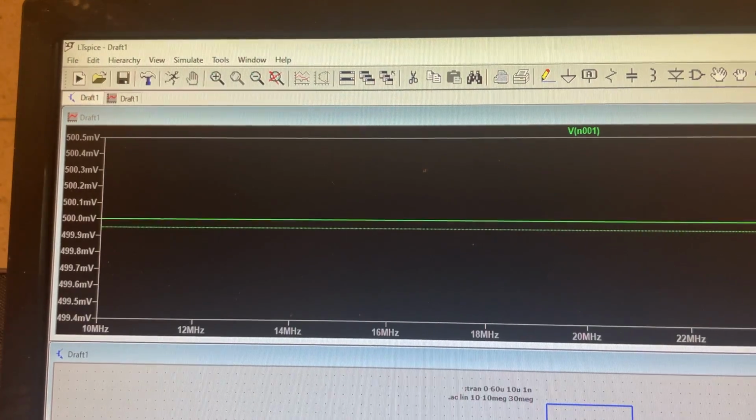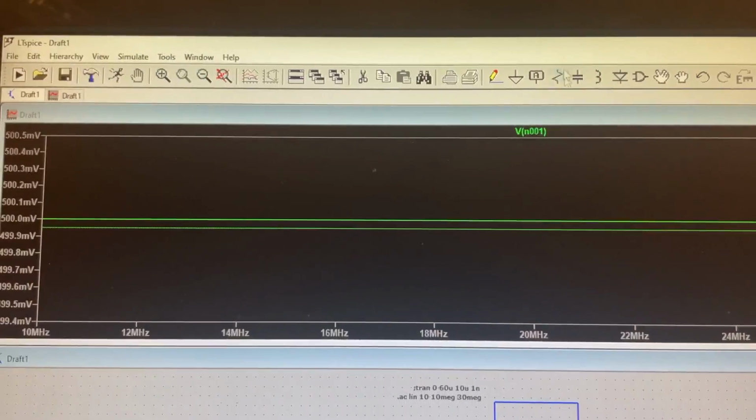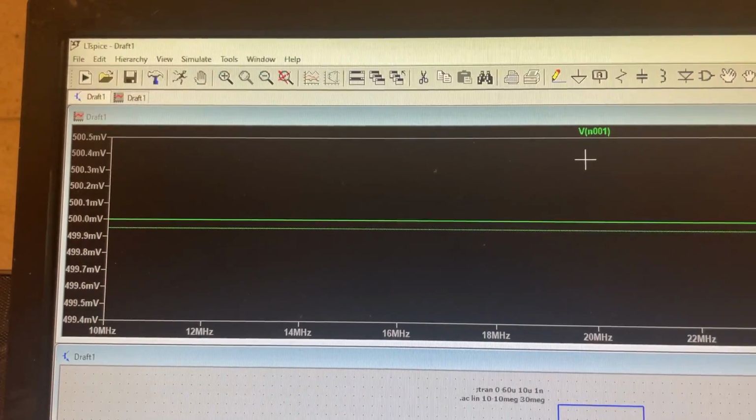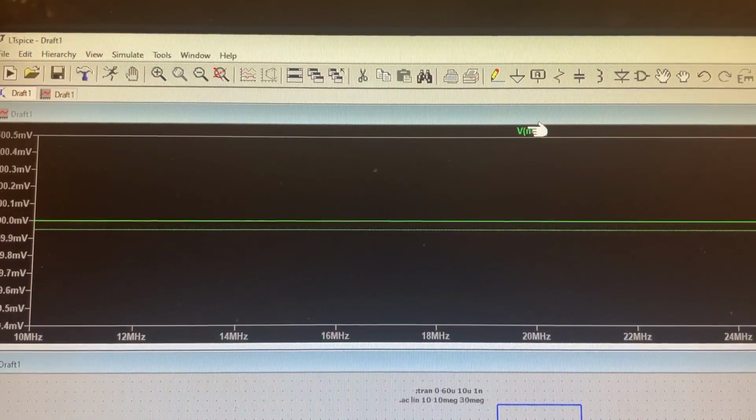Okay, so we want to look at the impedance, and we've got to apply Ohm's law here, right? If this was a DC circuit, then R equals E over I, right? So basically we divide the voltage by the current. Well, to measure the AC resistance, it's just impedance, but the formula is exactly the same. So Z equals E over I. So we're already measuring the voltage, as you see there, right? It's the same voltage that we got when we looked at the sine wave, okay?